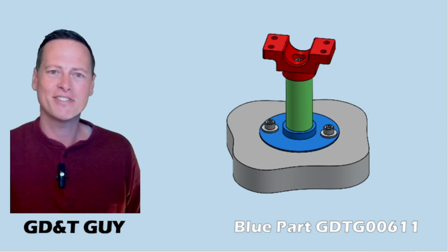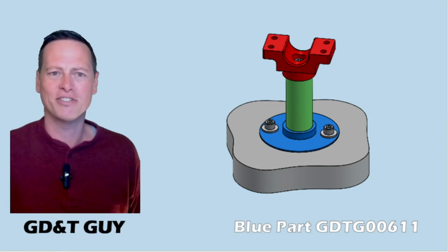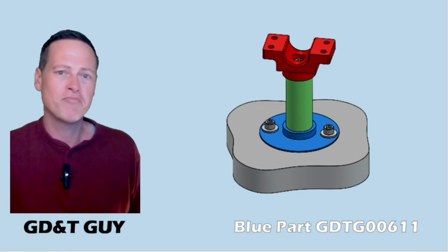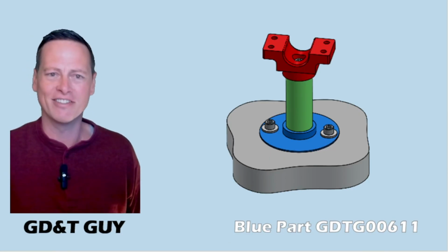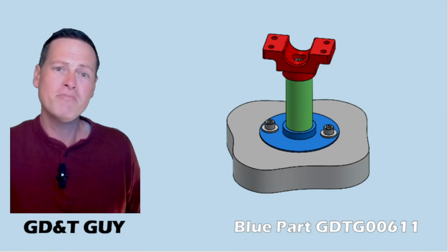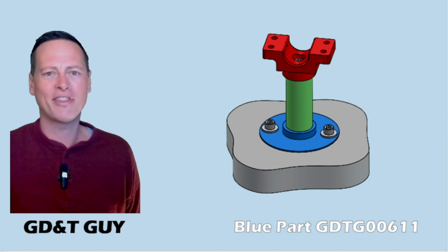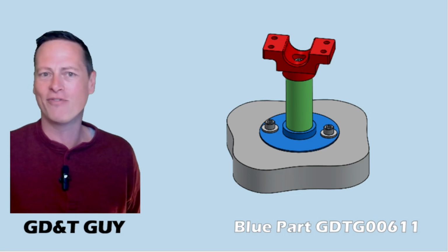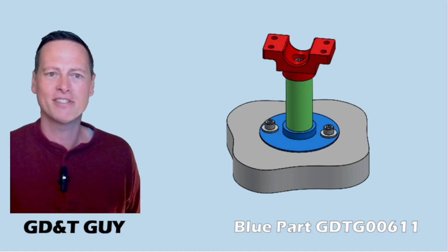Well, how about this? What do we say if it's decided that we don't really need the rotational constraint provided by the pin? Even better, that we don't have to drill and ream the holes anymore, or buy those pins, or press them in. Good riddance. With no more pin, it's pretty hard to justify the slot anymore, so it's going to go too. Now we can all look at this and know that there is a way to make these parts all fit together. This design seems to have a real place in our toolbox. It's something we want to be able to employ.